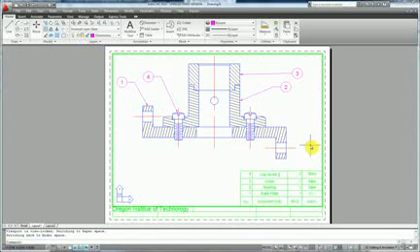In Chapter 11, we'll be learning about assembly drawings. This drawing here is an assembly of a bearing. It comprises a base plate, two cap screws, a bearing, and a collar, each of which is labeled with this multileader that references this table down here. This table gives a description of the part, the required number of parts, and the material each part is made of.